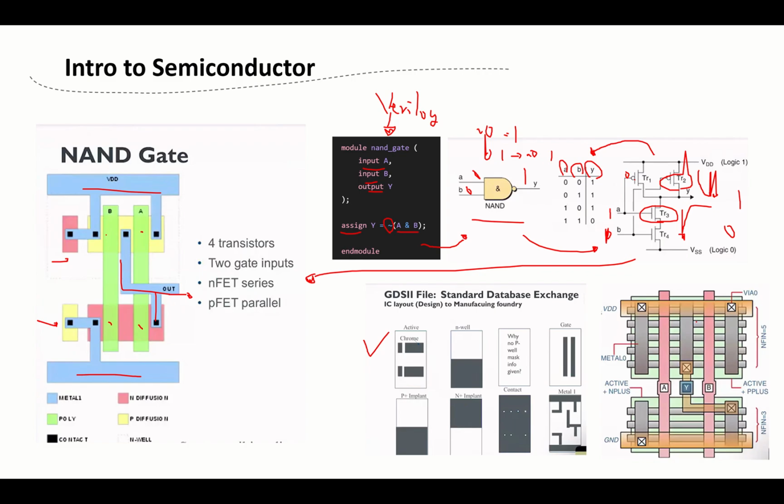Here we'll see a basic layout. We can see here's a VDD, and here's a GND for metal 1, and we have metal 0 to connect all the FinFETs, and here's a gate. So that's how they go from design, compile to circuit, then draw the layout. Based on this, it will be a different map, so the foundry can start making the chips by the layout.